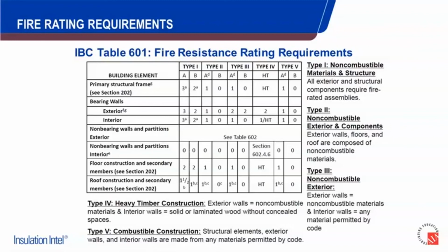Now, the point of mentioning this is these hourly ratings are separate from NFPA 285. So NFPA 285, as we'll get to here in a second, is strictly measuring flame spread via exterior wall systems when we're dealing with combustible materials. Now, of course, UL 263, there's tons and tons of testing out there. All types of wall systems, roof ceiling, floor ceiling assemblies, roof systems, et cetera. It could be a lot of different things, and they're not analogous with one another.